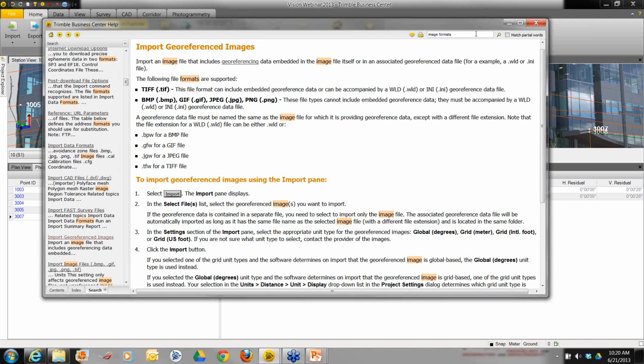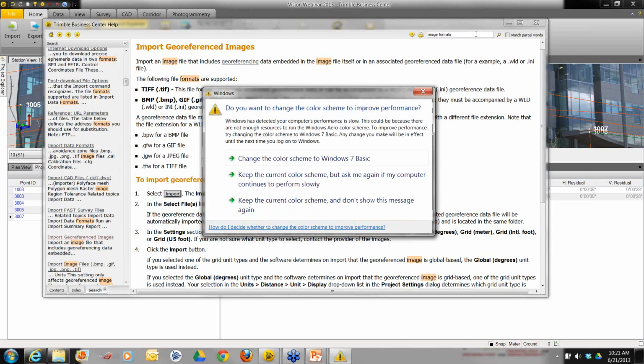But I kind of like that. Backdoor trick. Oh, sorry, Mel. Go ahead. I was going to say a backdoor trick, though, if I'm understanding this correctly, once you take the picture, there was no point information or point name or elevation on there. You can download aftermarket screen capture software that captures the screen, which ultimately is a picture, and then would have that information on there.